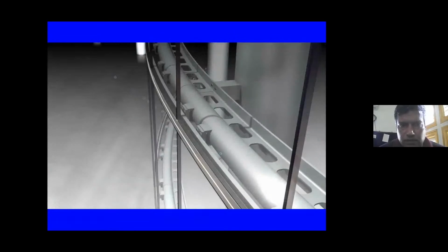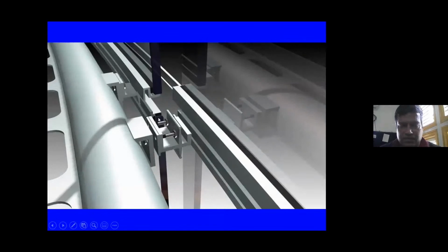These were our initial models before it went on to the site. If you really look at it, this was the portion, and this is the aluminum system, which is continuous, as it's a unitized panel. So this U shape will slide within this circular bearing kind of system here. So this was our concept to accommodate this drift in this concert hall structure.